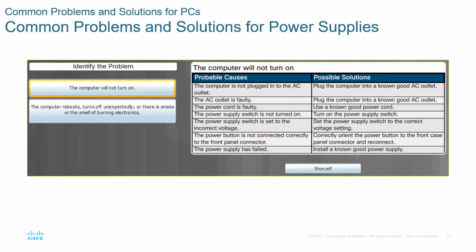Sometimes if you troubleshoot desktops and many issues with power supplies, it might be useful for you as a technician to acquire a tool called a power supply tester. It allows you to check all the power supply voltages and currents and make sure they operate at optimal values that are efficient to turn on your computer.